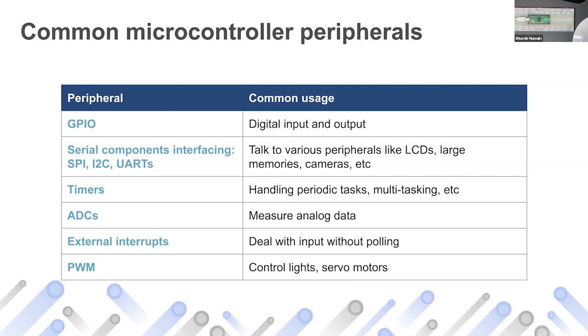And then you have PWM, which is pulse width modulation. It's a technique used to look like analog output, but really it's not analog. It's just a technique. For example, say you want to dim a light. In some cars, and I think most cars have this these days, if you shut the door while sitting inside the car and the lights inside start going off, they don't go off in one blow.